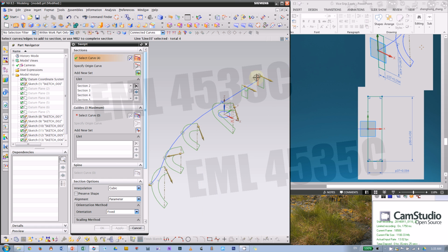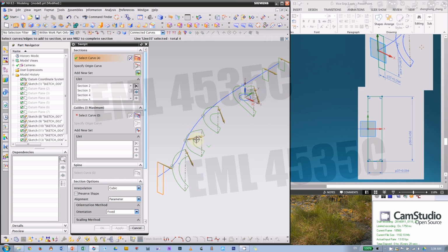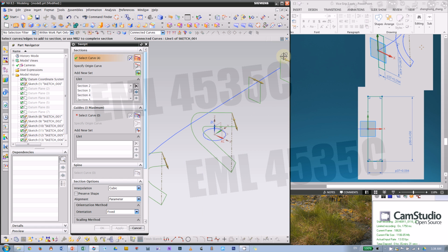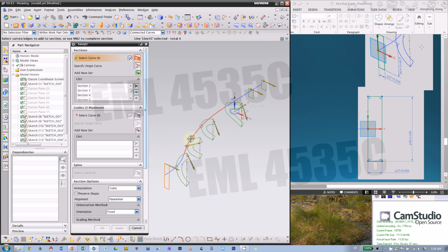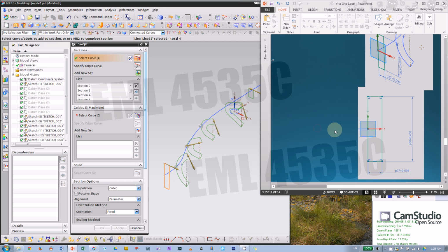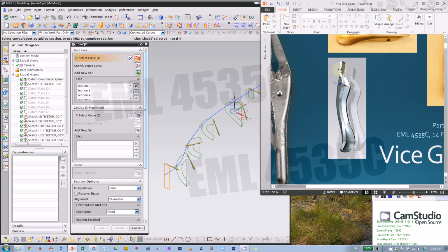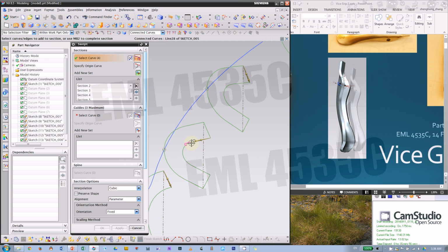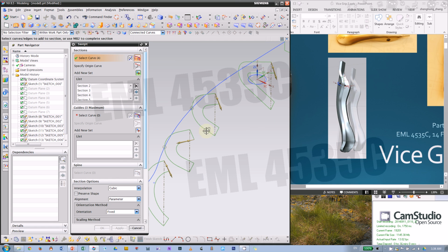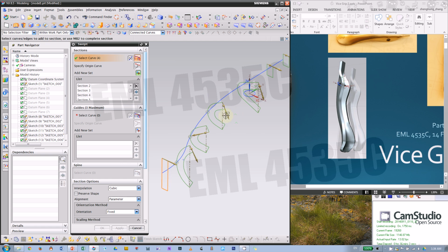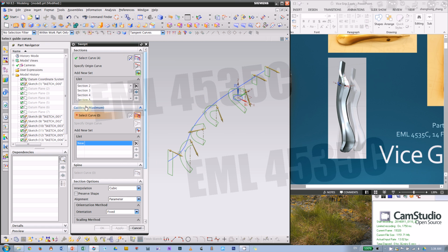So swept will keep those origin curves aligned. It'll make a surface from this top curve to this top curve, from the origin curve. Actually we can look at this, and you can notice this surface goes through those thickness curves. If I have this origin curve here, this surface will actually twist and go down inside the C shape, and we'll see in a minute. So for the guide curve, you can simply click 1 because we have only one, so that's pretty easy.